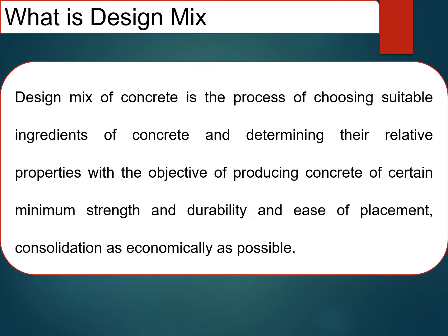That means generally in the earlier days we used to have the nominal mix, where you mix the ingredients at certain fixed proportions and do the concreting. There is nothing much you can do as far as the optimization of the concrete is concerned if you are using a nominal mix, whereas if you are going for a design mix, you can do the design based on the required strength and the workability. As per the individual's requirement, the concrete can be designed. This is the biggest advantage of a design mix as compared to the nominal mix of concrete.